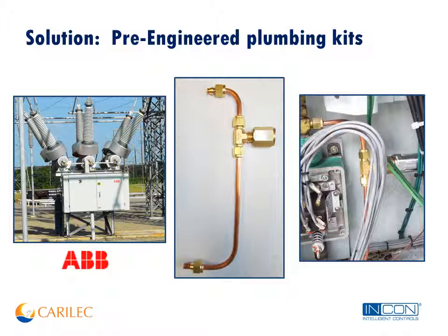So with our 25 years of experience, we know very well what is required for most types of gas puffer circuit breakers. So for instance, here is an ABB PM style breaker. We've pre-engineered this tubing and retrofit kits for the sensors, and it makes it very easy for a field crew to install. You can see the picture in the middle is the actual part, and on the right is the part installed, and on the far right of that picture is the silver gas sensor that we use.